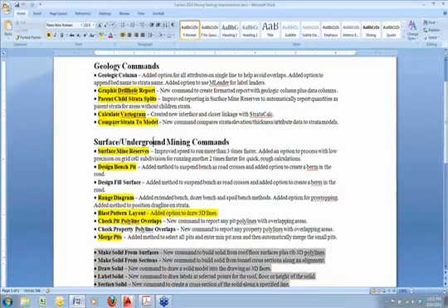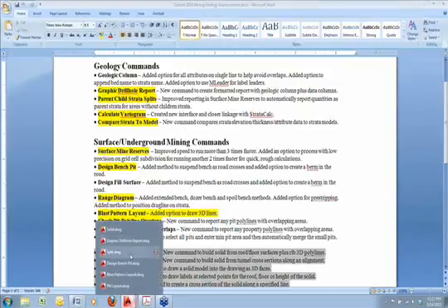Next one. Kind of a small minor command, but it's pretty powerful actually. It's compare strata to model. This looks at surfaces and drill holes. And so let's say you were maybe given some surface grids from an external source, and you wanted to compare them to the drill holes very quickly and easily to see how close they matched. This is a useful tool for that. Another use would be comparing the drill hole collar elevations versus the surface topography. That's a report we've always had, but this one is very similar. It works at the subsurface level.